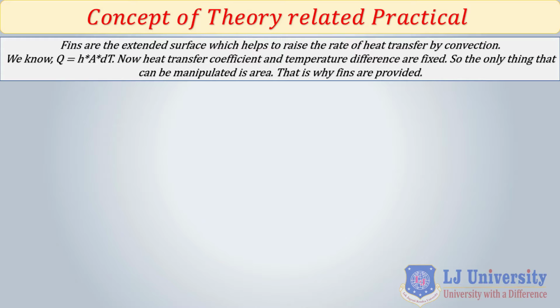But why are you able to do that? Because, yes, you are right, you have increased the surface area. First of all, you have tea in 1 cup, so the surface area is less compared to the very big pan, which has a very big surface area. So if you increase the surface area, the rate of heat transfer increases. That means how speedily the heat will be transferred. That is what the rate of heat transfer means. So the additional surface that you are taking is known as fin. So additional surface, or you can say extended surface, is fin.